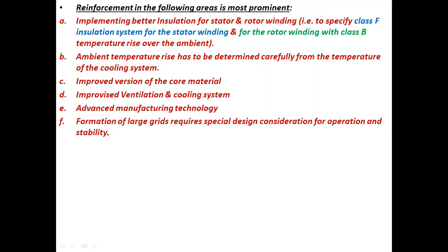A. Implementing better insulation for stator and rotor winding, that is to specify class F insulation system for the stator winding and for the rotor winding with class B temperature rise over the ambient temperature. B. Ambient temperature rise has to be determined carefully from the temperature of the cooling system.